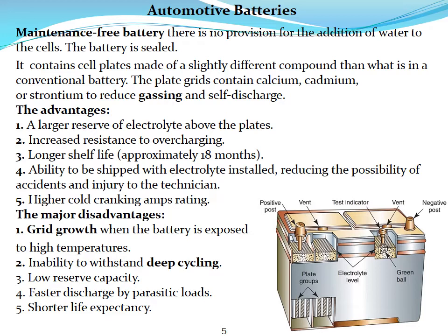The advantages of this cell: a larger reserve of electrolyte above the plates, increased resistance to overcharging, longer shelf life, approximately 18 months, and the ability to be shipped with electrolyte installed, reducing the possibility of accidents and injury to the technician.